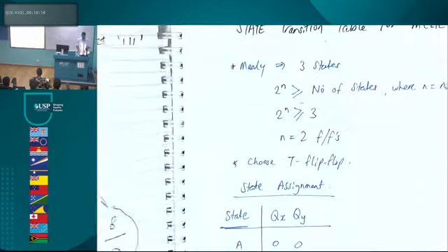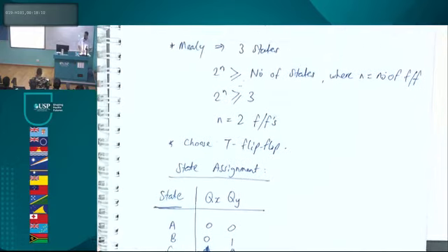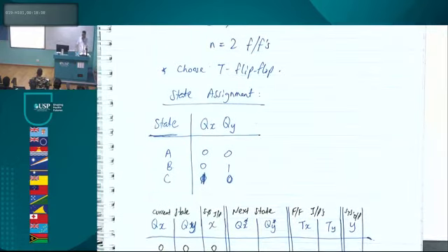Guys, when you have a look over here at the state assignment, what comment can you make with regards to number of states and number of flip-flops? What's one particular piece of information that you pick up? Yeah, one is unused. One state is unused, right? So the good news is that when we do sequence detectors, unused states can be catered for.